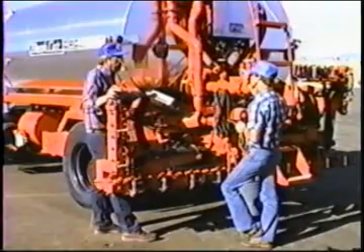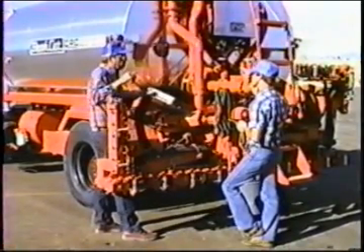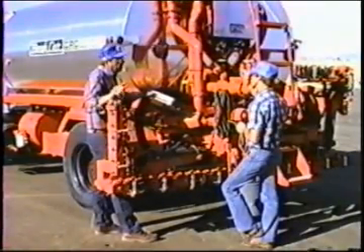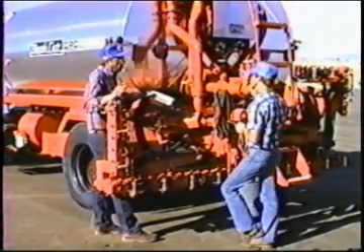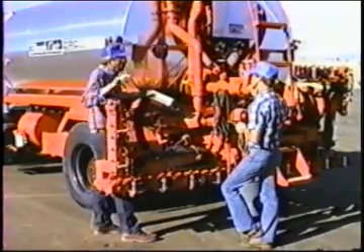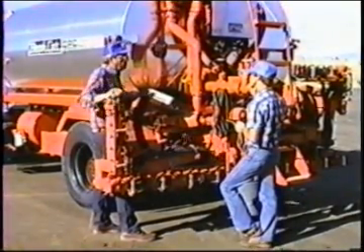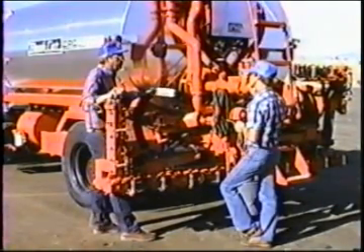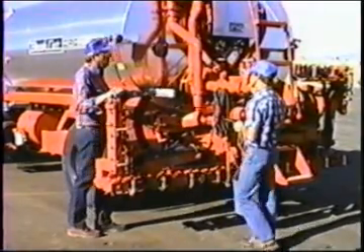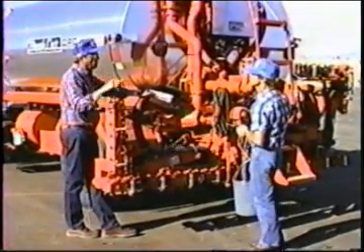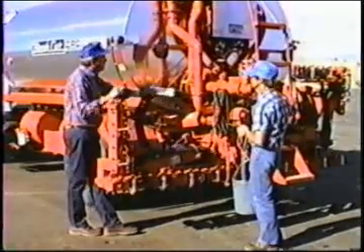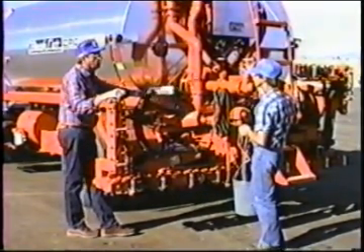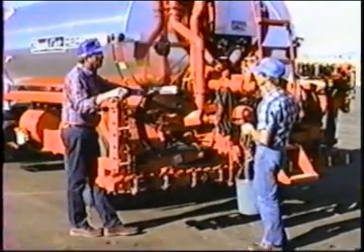And if it's slightly off, let's say that we make our initial setup, then we take off spreading, and we see that at 400 feet per minute we only have 125 gallons a minute. While we're spreading there, just dial the pump up and get it on that 135 gallons a minute while you're in actual operation. Double check your initial setup. And always do that for any manual setup, because there's some inaccuracies both in the truck engine tach. It's not extremely accurate, and this chart is just filled in to the nearest 10 gallons per minute, so it's not exactly accurate, but it's plenty accurate to start out your shot with.